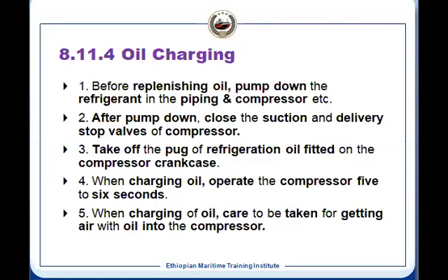It means your crankcase pressure. You connect your oil line, which will be filling the compressor crankcase, but your crankcase is pressurized by the refrigerant, because your crankcase will always be pressurized by the suction pressure. That means the refrigerant pressure. And once the refrigerant pressure is there, if you are charging by gravity, then what will happen? You'll have to create a vacuum in the compressor. Once you create a vacuum, meaning lower pressure than the atmospheric pressure, then only you can charge the oil by gravity.